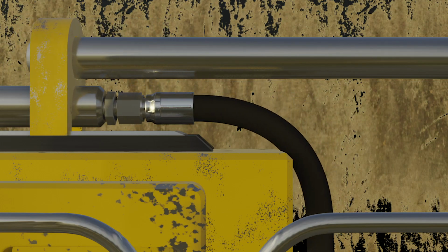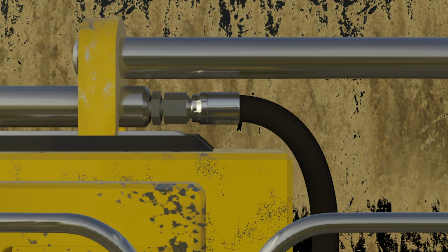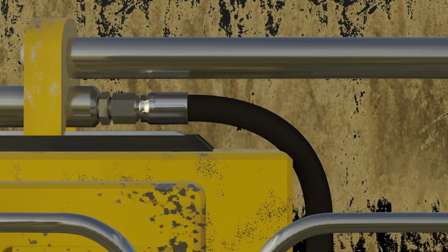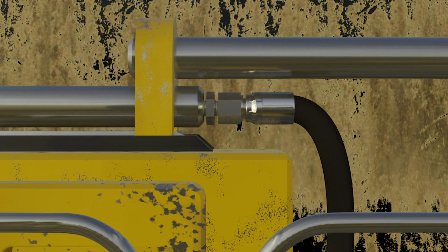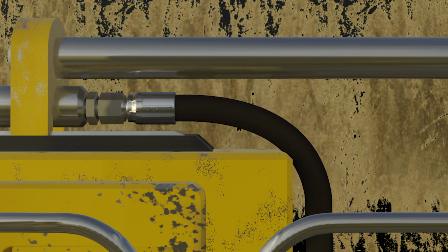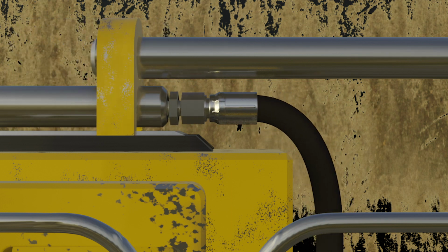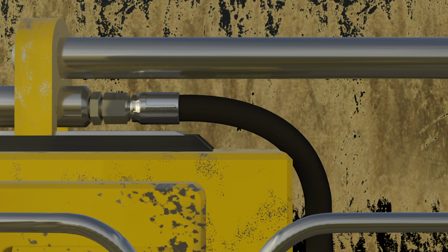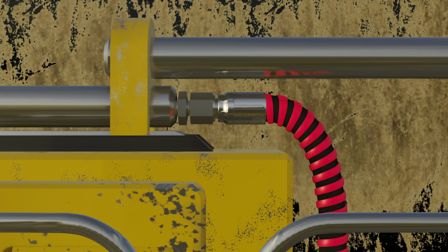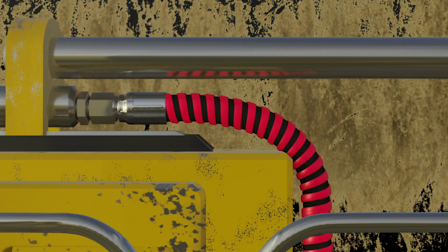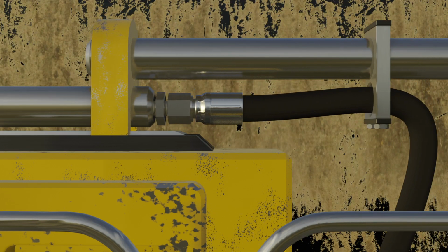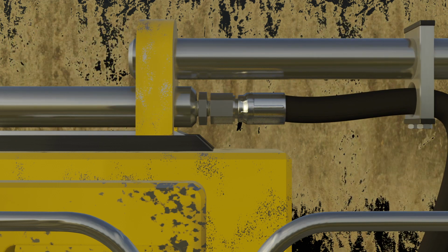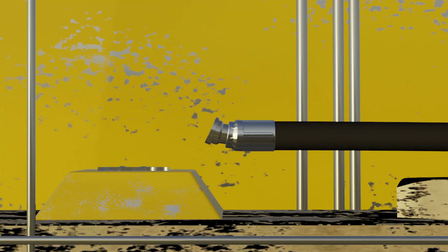Looking at this example, the problem here being that the hose is rubbing on a sharp corner. What will happen to the hose, and what can you do to improve the situation? The hose is going to suffer from abrasion. The outer covering and the reinforcing layers will be adversely affected, allowing the medium to burst through the side of the wall. One easy method to reduce the problem is with the use of a spiral guard. A better idea would be the use of hose clamps to keep the hose away from sharp corners and moving parts.